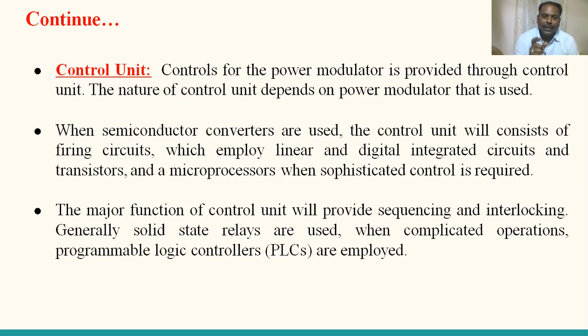The pulses are given to the rectifier in such a way that T1 and T2 are in one sequence, and T3 and T4 are in another sequence. In a particular span of time, those are interlocked and then given to the required thyristors.